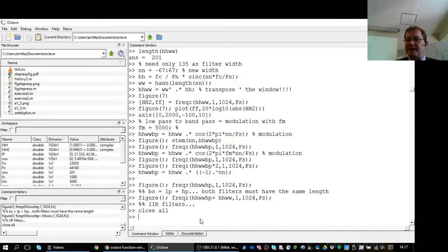So earlier we had this notch filter. Maybe I should take a picture of that one and then draw something there. So if you have made a spectral analysis and find out, okay, there is a funny peak at the middle of it and you want to get rid of it, maybe some interference noise from some source, this band stop notch filter is then a good solution.